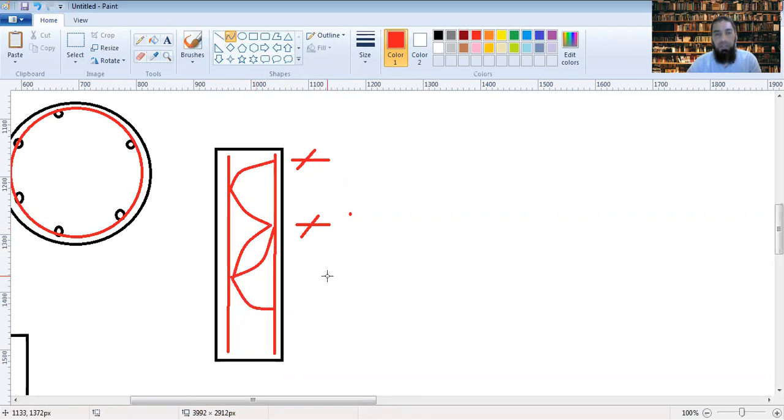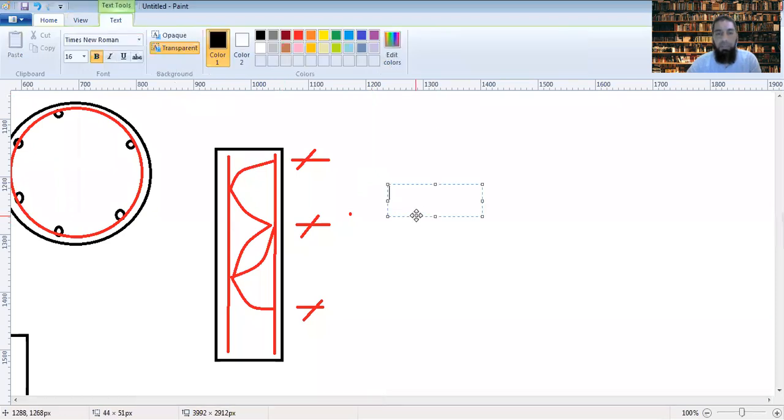So the pitch will keep on being taken from this point up till this point, or you can take from any point, but at the same position in the next turn. So it becomes one pitch. And what is the minimum pitch that you take? Minimum pitch is 75 mm, and the maximum is 300 mm. You do not exceed. Minimum is 75 and maximum is 300.